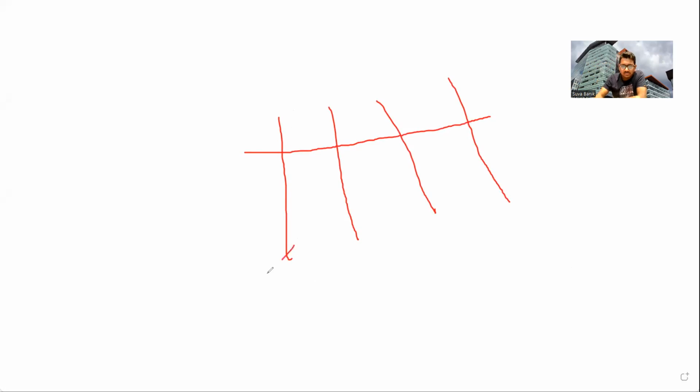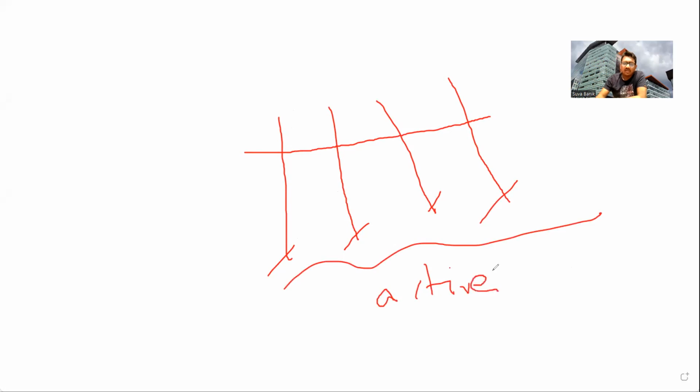This is the poly layer I draw here. The vertical layers are poly, and every one of these 4 transistors is an active transistor. In the ion-implantation process, let's say this is my drain terminal, and this is also my drain terminal. Due to the ion-implantation process, these active transistors have some impact. I will explain what impact later.